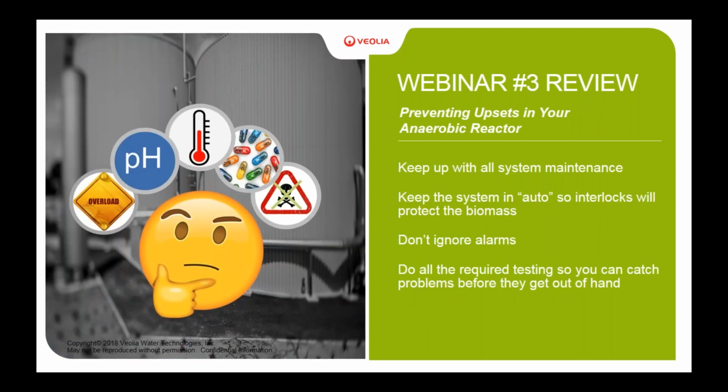And finally, in our third webinar, we tried to look at some of the things that cause upsets and how to prevent them. A lot of it being keeping up with your system maintenance, keeping up with calibration of pH probes, looking at temperature transmitters, etc. If you have a SCADA system and you have automatic control, try to keep as much as possible in auto and not put things in manual.